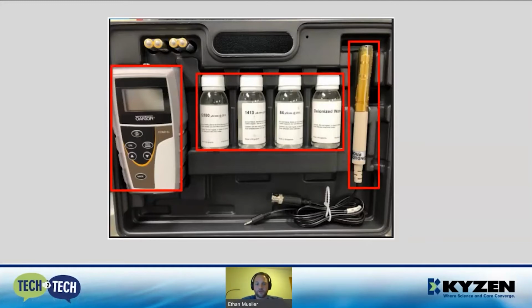Once we're ready to use this, the first thing we're going to want to do is collect a sample from our machine. Then we're going to want to take that sample and set it aside to cool down to ambient temperature. The conductivity of the solution will be affected by the temperature, so we just want to remove that variability.